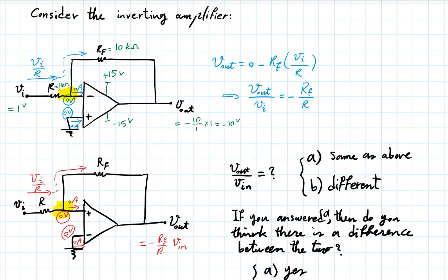The first circuit has a negative feedback. What happens through this path, if you have a small change at the input due to whatever you have, even noise, that change going to the output will be fed back in a way that the output will change in a way that when translated back to the input, it will oppose that instability, that change.